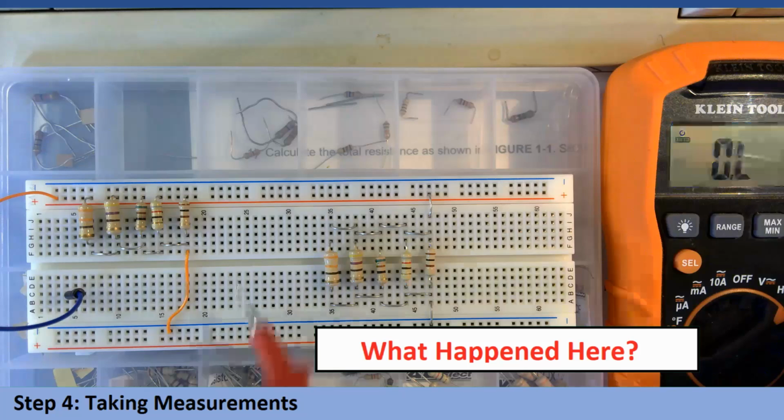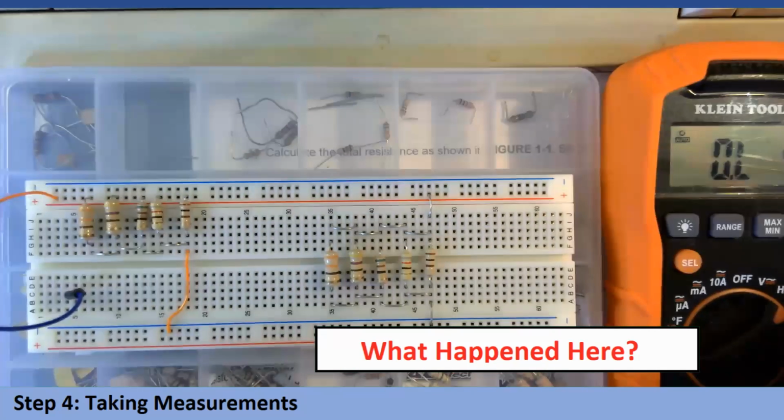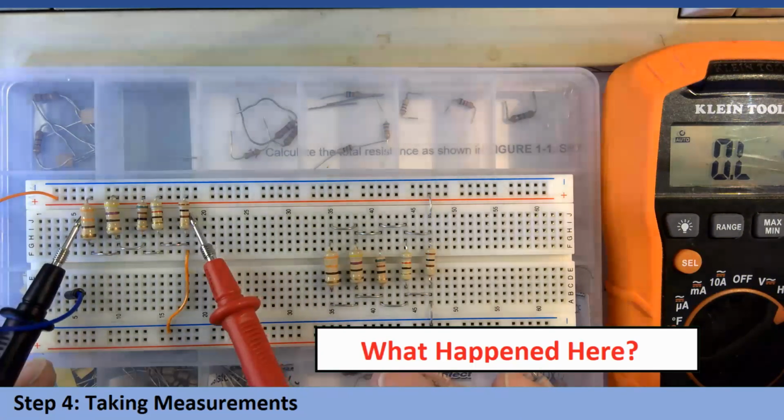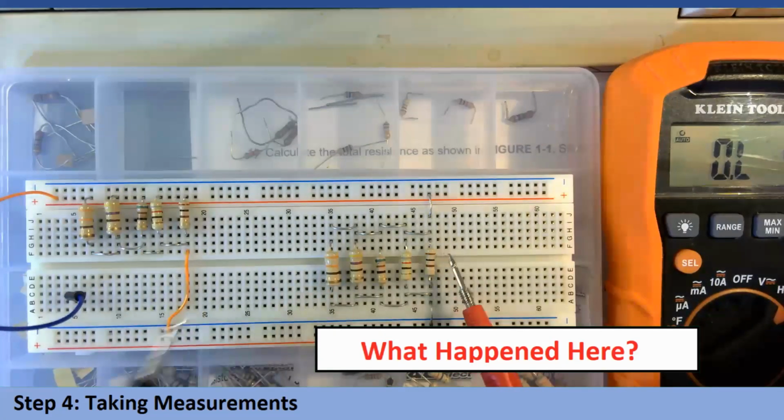I had left a jumper from the demonstration of the alternative method of setting up the parallel circuit. This ends up that I have this in parallel with this. And since their resistances are fairly close, it's like taking the resistance and dividing it by 2. So if I take my 11 and divide it in half, I come up with 5.5 ohms.